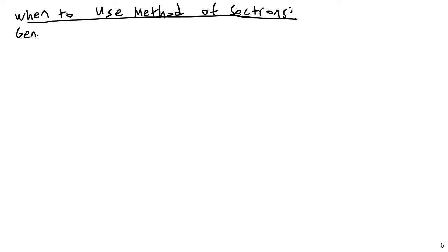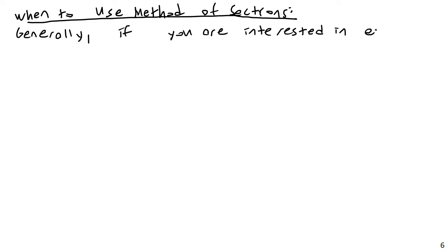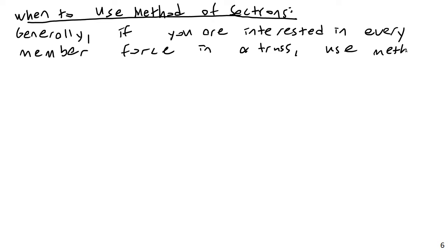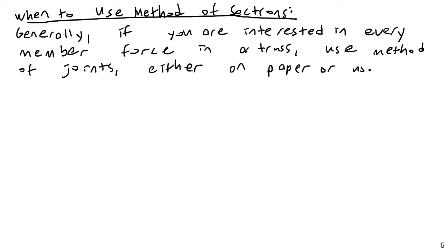Generally, if you are interested in all the forces in a truss, in every force in a truss, use method of joints, either on paper or using matrix methods.